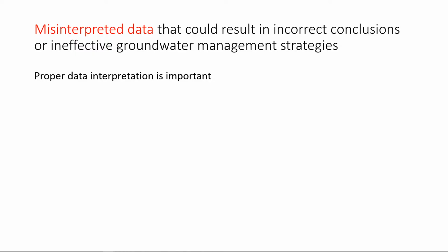It's just that you need to understand that if you are pumping near a stream, you need to account for this, and you need to understand the methods that account for this, as we studied them here in this lesson. Without understanding, you may misinterpret the data or think that there's something wrong with your pumping test. Well, your pumping test is fine, but you just don't understand the well hydraulic effect of boundaries or a leaky aquifer or things like that.